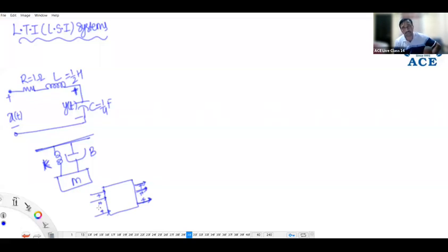Because of these two reasons, the LTI system is taken as a separate classification. When you take a sum of inputs, it produces a sum of outputs, which is linked to superposition. Output may be a shifted version of the input, which is linked to the time invariance condition.